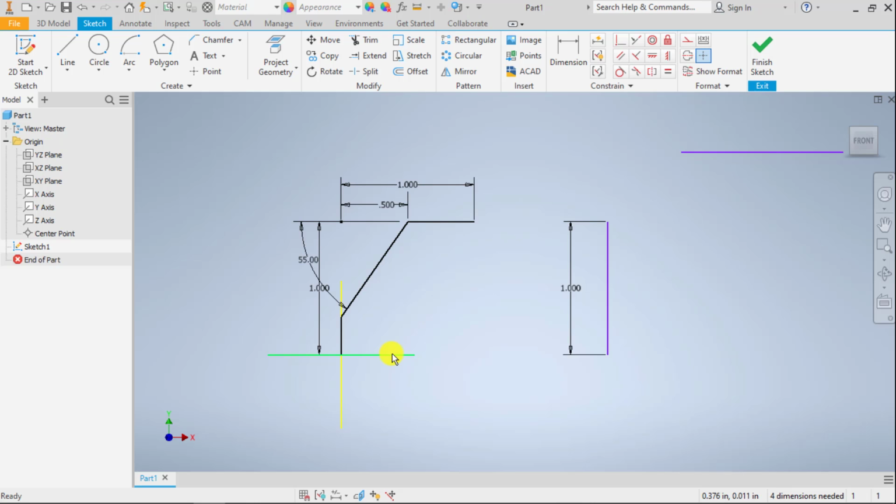I prefer to do them in the part, in the solid. If you're in a situation where you have to do it in a sketch, it's perfectly okay. It's going to depend on your part, your workflow, and what your requirements are. It's typically easier to use chamfers and fillets in part mode, and we'll cover those down the road.